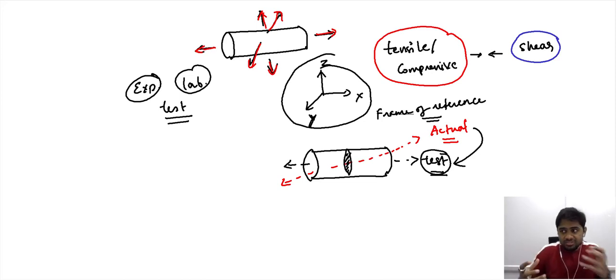One definition of stress that we gave is the resistance offered by the material to the imposed mechanical condition, and this resistance is often discussed along this particular cross-sectional area. So, in the framework of the test condition, the area of our interest is generally this cross-sectional area, and now we have a loading condition that is inclined to this cross-sectional area.